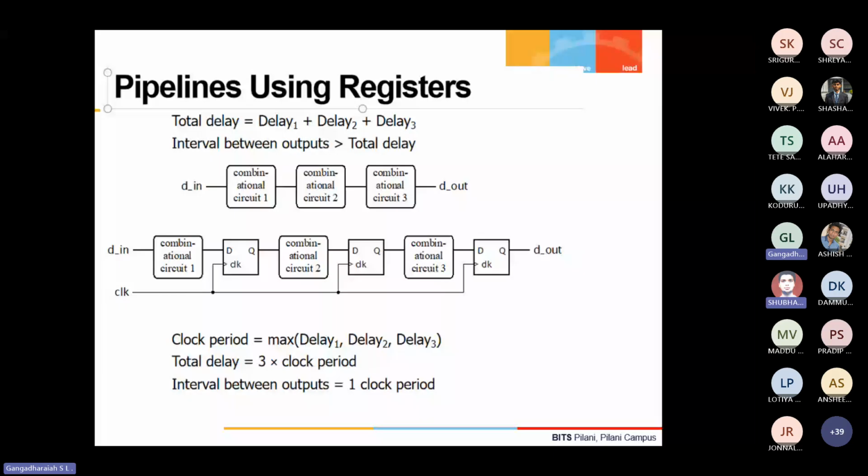And sir, one more issue: for one endpoint, there are 700 start points which are failing. That is because of pipelining only. If we fix one start point for that endpoint, 699 start points are still left. That issue is because of pipelining only, something happens in the pipeline. Yeah, definitely. Shall I proceed?